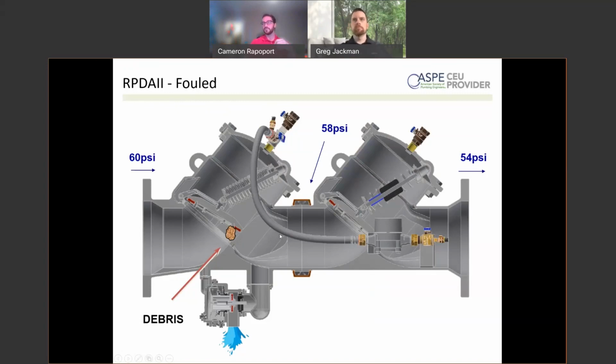So this is really where you get a big difference going from a type 1 to a type 2, because you don't need a relief valve in the bypass. It's 2 less things to foul. It's 2 less things to test when the testers come in, and it's one less thing that has to go into the bypass. So I really encourage you guys to take a look at these. They're pretty interesting, and they've been certified for use, like I said, for almost a decade.